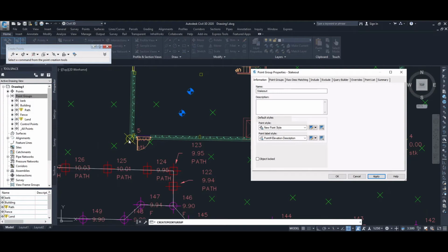Okay. Now for these 4 points, we've made the location of them and we have some text beside them. The normal text is the point number, the elevation and the code. For these points specifically, we're going to change the standard text that is written beside each of the points. In this case, you can see this one highlighting as 0.5, the height is 0 and the point description code is STK. I'm going to change the text that is shown beside each of these points.